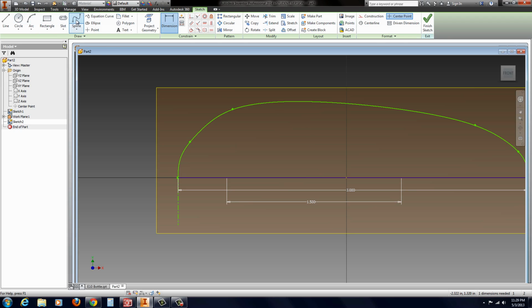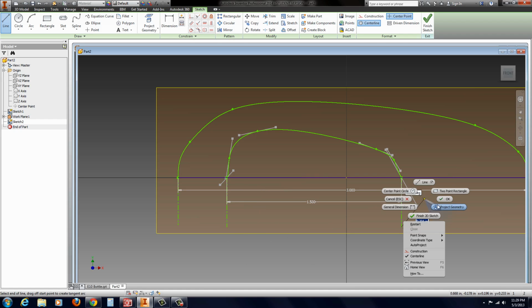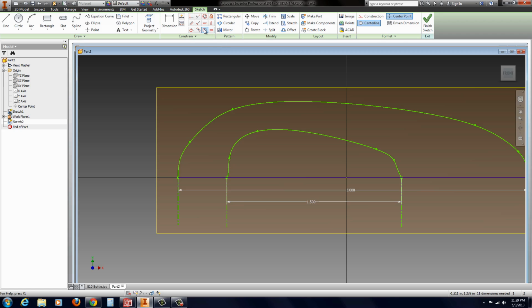And then we'll take the spline tool again, same one we used before, interpolate. And roughly around the same number of points is probably a good idea. And now we'll go ahead and select the line and center line. Use our same little trick to smooth out those ends. And curvature continuous, smooth.